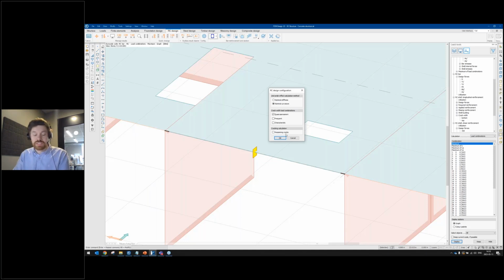And if the force exceeds this limit, the section will be assumed to be cracked. But it can be a case that a structure has been subjected to a larger load in the past, and it's already cracked, and you want to calculate the crack width of reopening of these cracks. Then you can check this checkbox and assume the whole section, all of the model, to be cracked once. So this will mean that you will get crack width in every part of the structure except for parts which is under pure compression, basically. But we don't want to change that in this case. We will go with these settings.